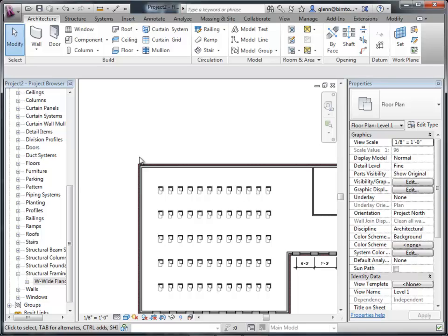When we're going through creating floors, it really is a very simple operation. It looks the same for roofs. In the same way that when we create a wall, we draw a single line, and after we draw that line, a wall is created that meets the different type characteristics we gave it. To create a floor, an area as opposed to a linear thing, we basically trace the boundary of an area, and it'll fill in floor between those things.